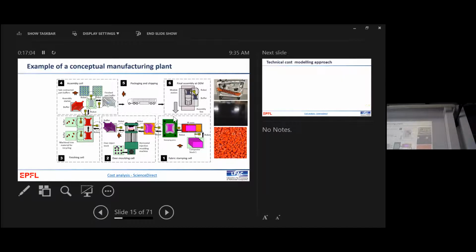This is a production line at Mercedes, and we included this in the model, the cost to manipulate the part and put it into the body in white. So you have an apples to apples comparison between the incumbent, in this case magnesium, and the real parts we're looking at here in composites. This is critical to draw your process flow. If you don't do this, you tend to get completely lost.